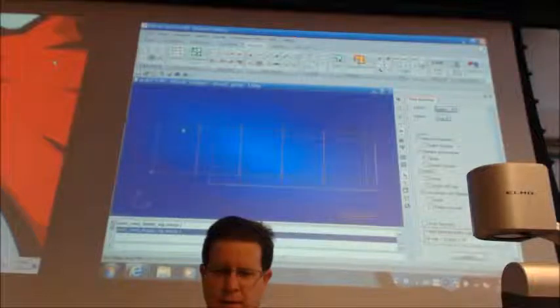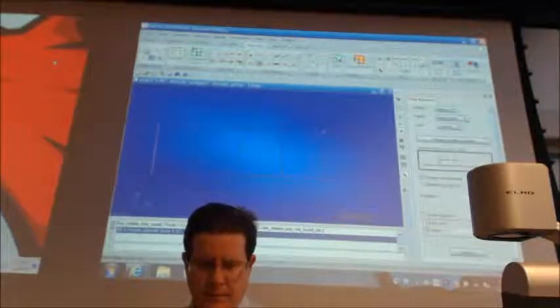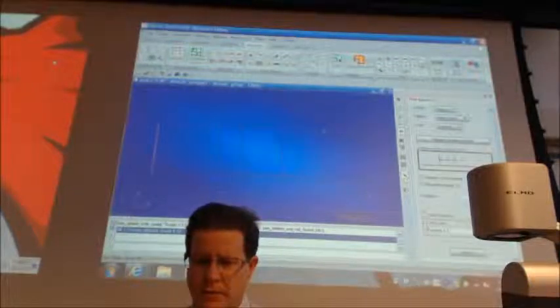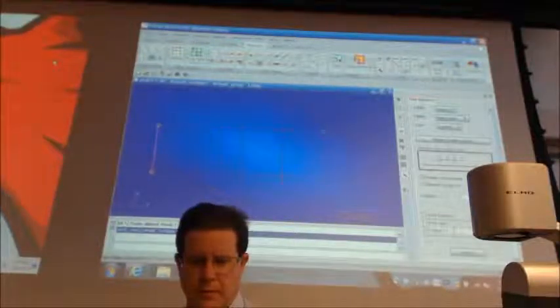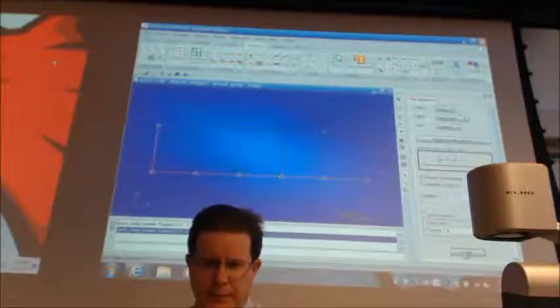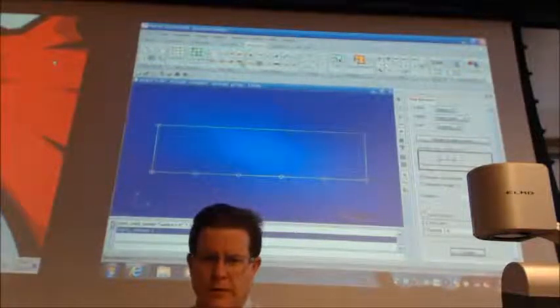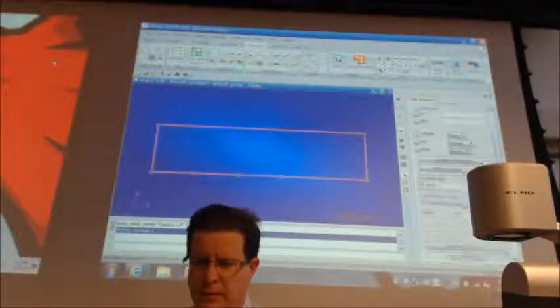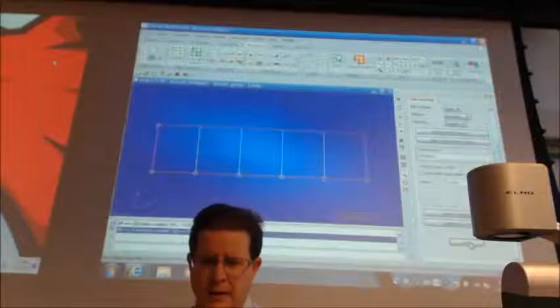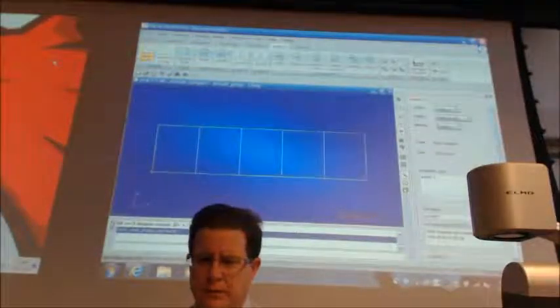Just delete everything again. Okay, surface, do quad 8, surface 1, apply, analysis.